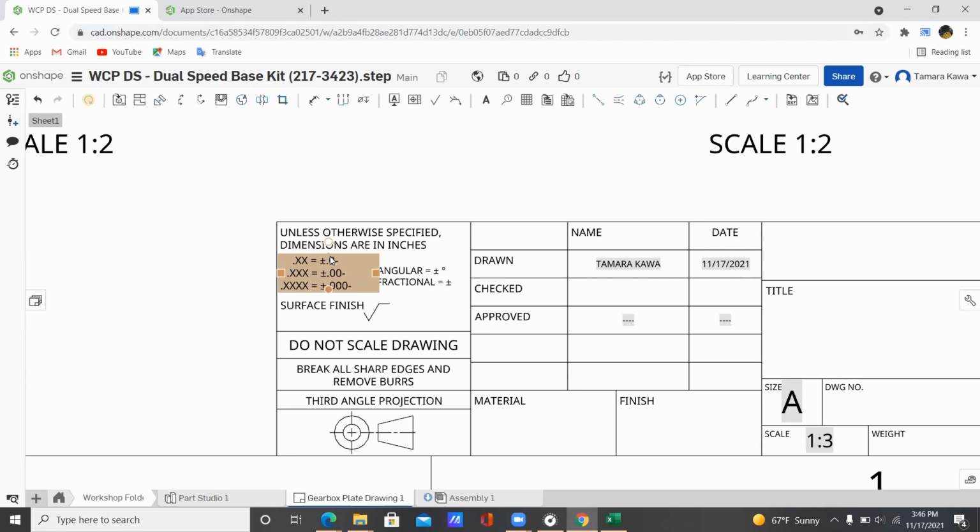So what Faye just said is it's like you're sewing and you try to give yourself some seam allowance, basically how much you're allowed to be off before a part is rejected. And yeah, that's actually a really good analogy because at work when I send out machine shop parts, you don't always send out everything with 3 decimal places because that means really high tolerance. It means it takes longer to machine, it's more expensive, you're throwing out more parts.